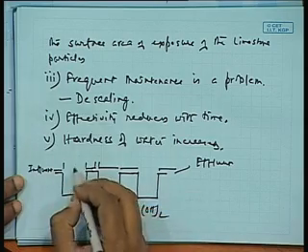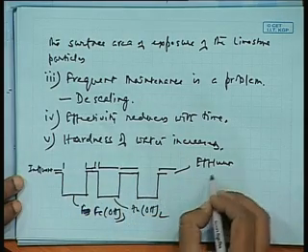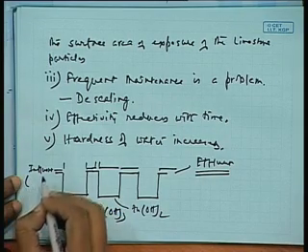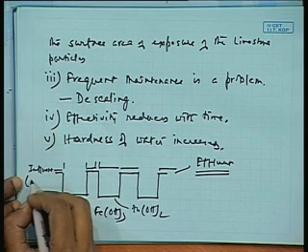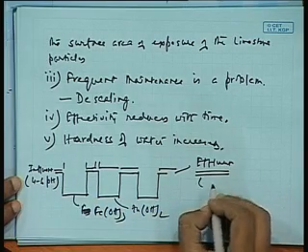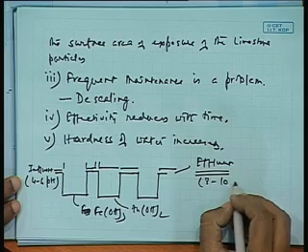So by selectively maintaining that, you can precipitate a number of these substances. But the influent pH may be say 4 to 6, whereas the effluent pH becomes 8 to 10 or even 8 to 11.